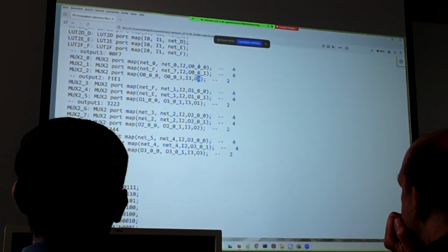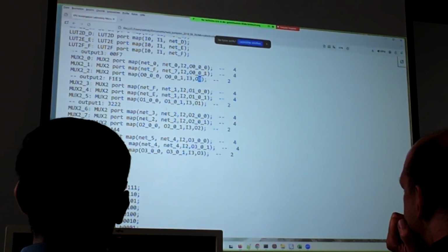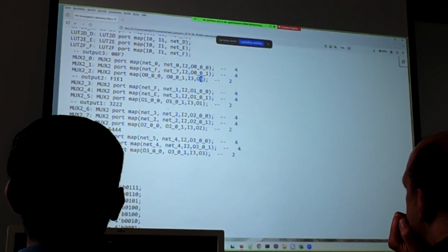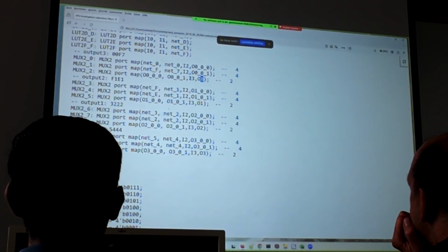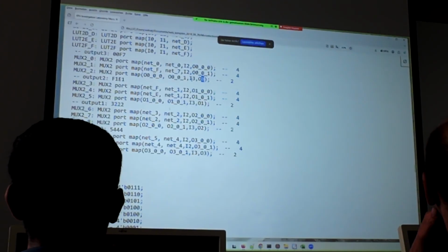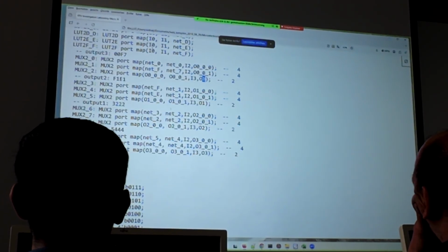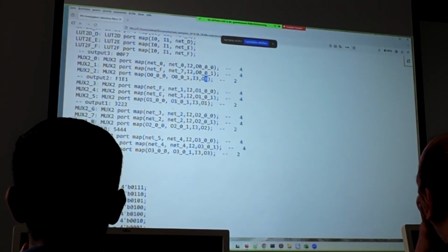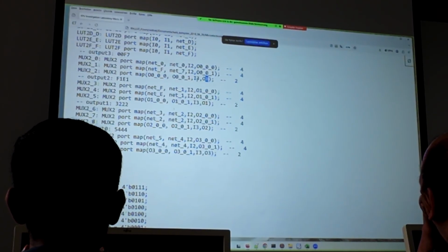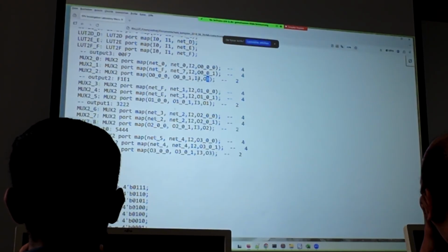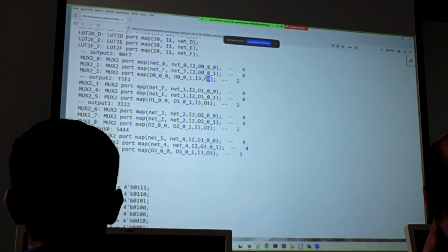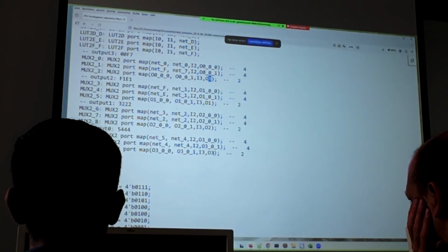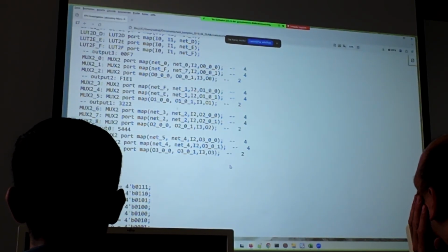I get the outputs here of the first multiplexer stage, and then I combine these to my real output. And everything will be selected by my input 3. Because the input 1 and input 2 are used here, the input 2 is doing then the second multiplexer stage, and the input 3 is doing the last stage. And then I have the same for the output 2, for the output 1, and for the output 0. And unfortunately, I have to fix this one. Okay.